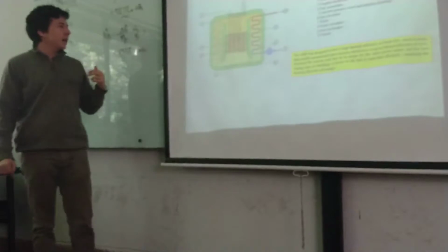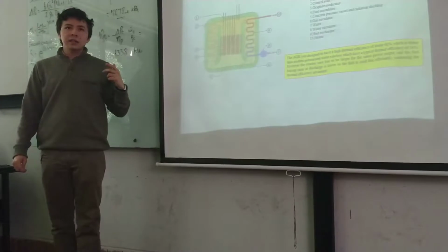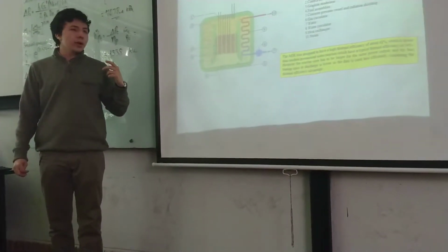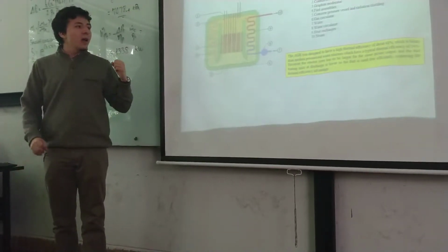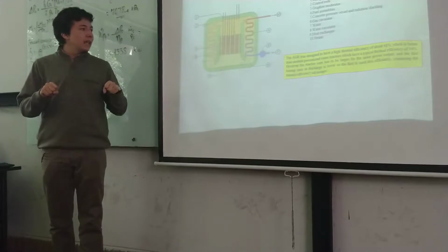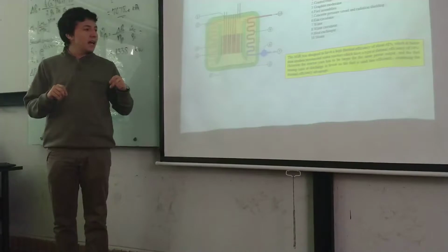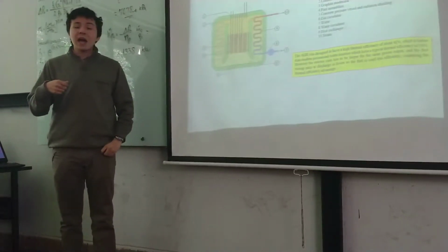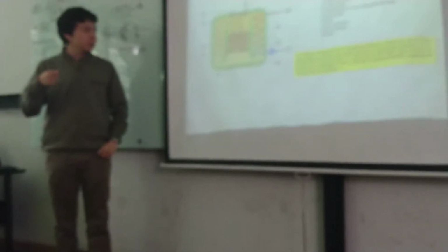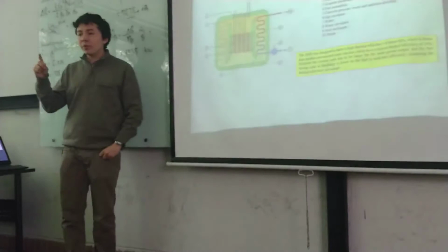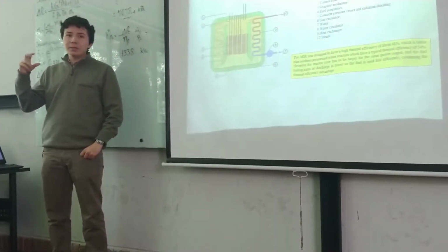Here we see an advanced gas-cooled reactor, where we use CO2 not as moderator but as a coolant, and we use graphite like a moderator of the reaction. The difference of the system here is that it can reach a higher temperature because we are using CO2 as the fluid of heat exchange. If we remember, CO2 or gases have a higher Cp than normal fluids.